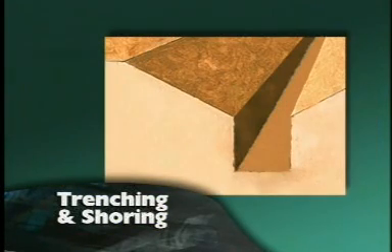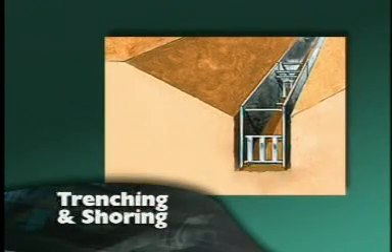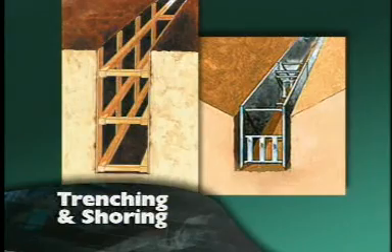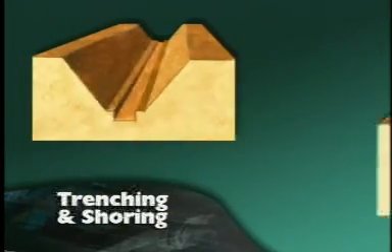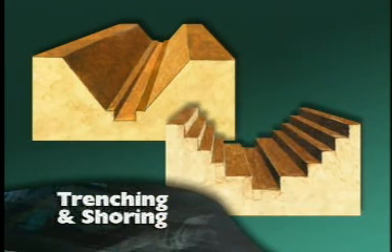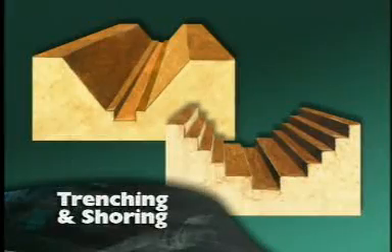If the trench is more than 5 feet deep, employees must also be protected by an adequate cave-in protection system. This can mean installing structural supports, such as a trench box, or using a sloping and benching system. There are various OSHA rules for sloping and benching, depending on the type of soil and size and depth of the excavation.